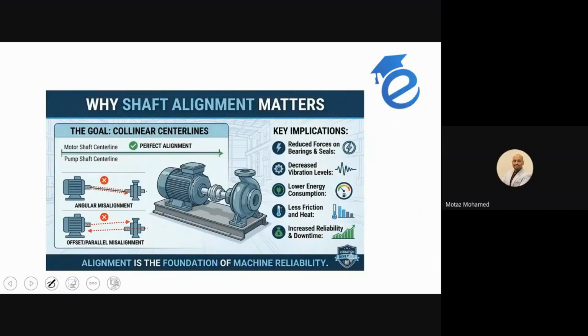And the last part of our course will be shaft alignment. Our course is actually divided into 3 parts. First one is vibration analysis, starting from signal processing, measurement, diagnosis, and the different techniques you use to diagnose different machine defects. Second part is balancing: how you balance, how you decide or measure the balancing, how you calculate the corrective mass, and what standard we have to follow in order to judge the acceptance or rejection of this residual imbalance. Okay, how you read the balancing report.